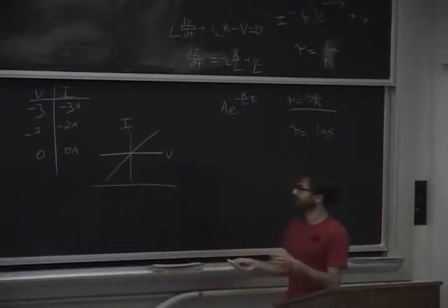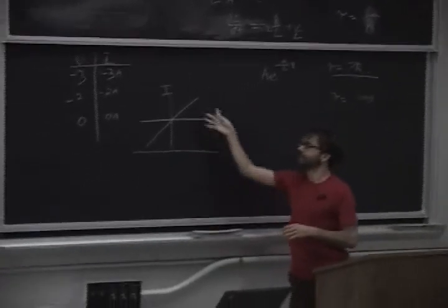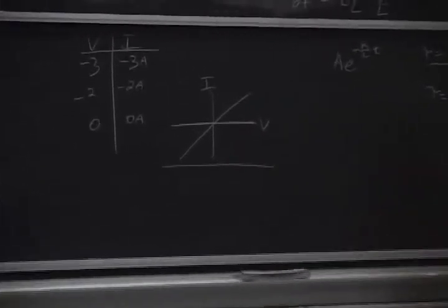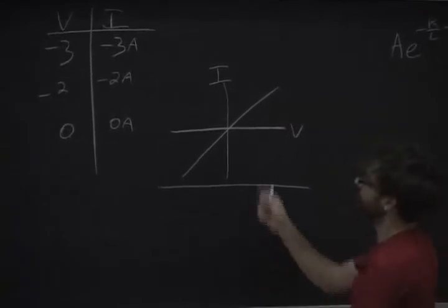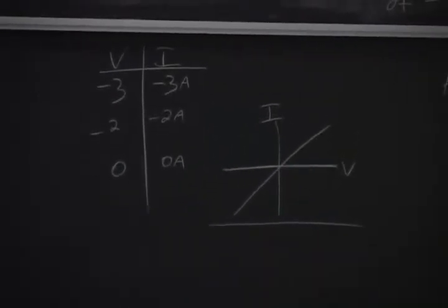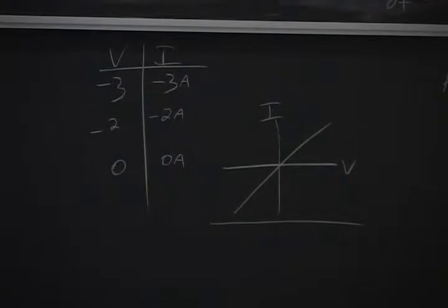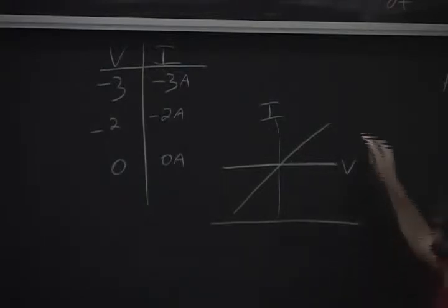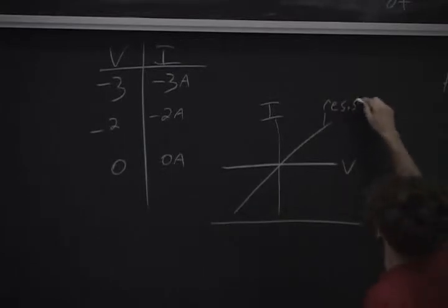So we're happy with this, though, right? Basically, if you took an inductor and you did this, you get this characteristic, right? So does this mean that the IV characteristic of an inductor is shaped like a resistor's? Yes? No? What's the slope coming from? Exactly. So what you're seeing here is basically the resistor.